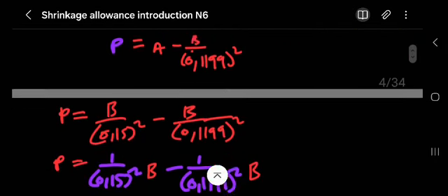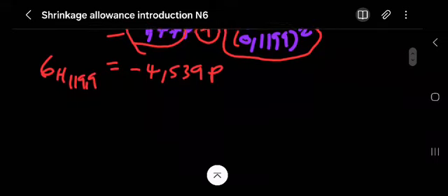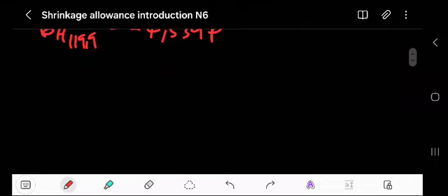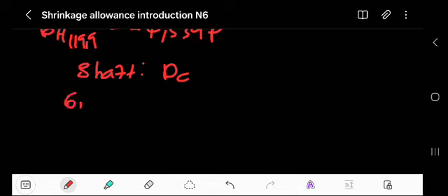Since they will be equal, we know that at the shaft, at the common diameter, the radial stress is equal to the hoop stress, which is equal to the pressure.